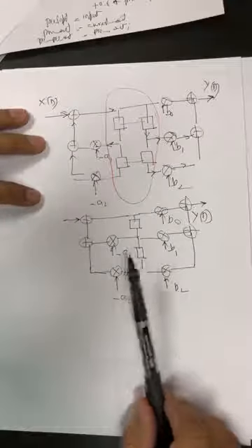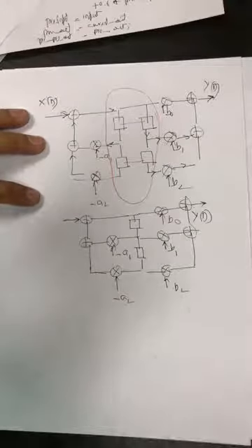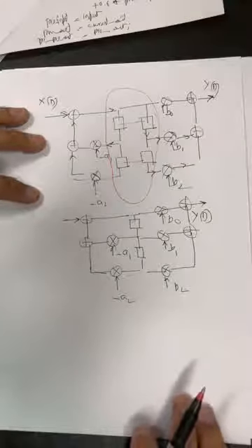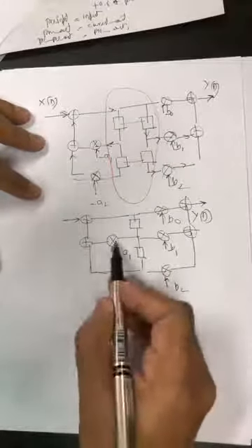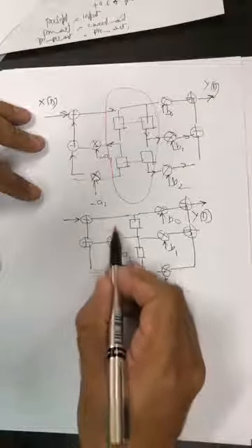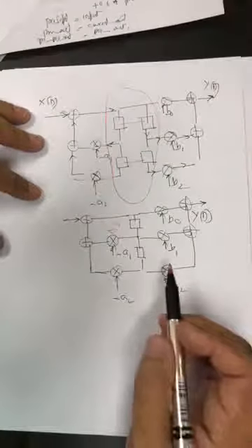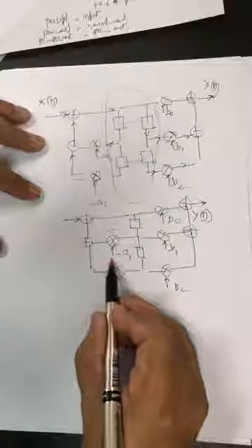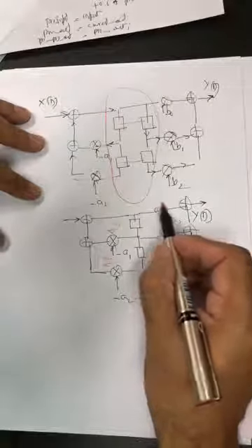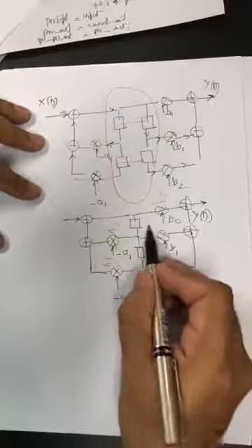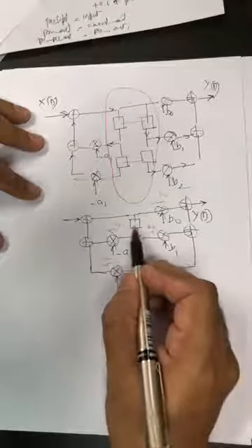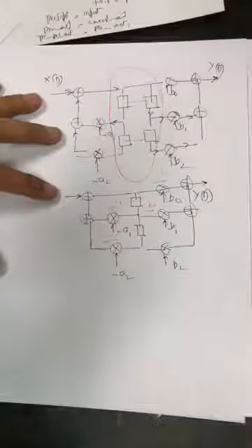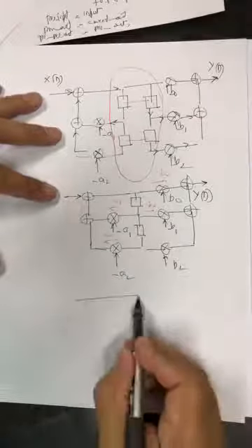And we also know that instead of this, we sometimes want to draw a signal flow graph. In a signal flow graph, a multiplier is shown with an arrow, and we put the A1 here with an arrow, and we put A2 here with an arrow, we put B0 here with an arrow, B2 here, and delays are represented by Z inverse. So you can redraw this.